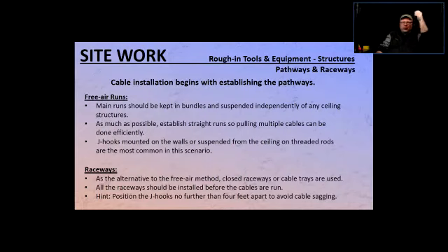So when you put the ceiling tiles, the metal grid is suspended on metal wires, right? So it used to be that people would just, and you're still going to see that done from years ago, in some cases, that the wires will be tied to those wires that are holding the ceiling structure. Well, that poses a danger.